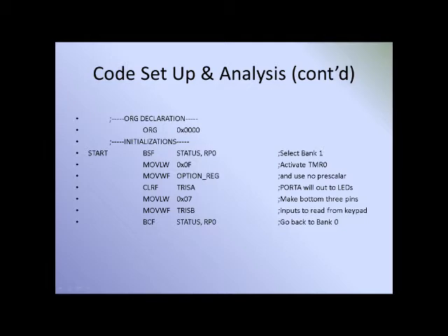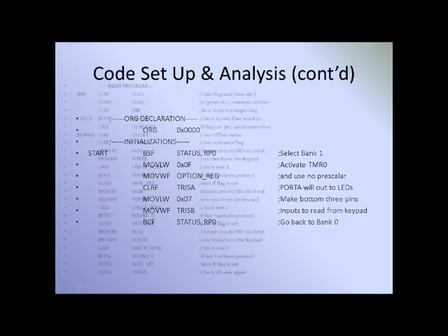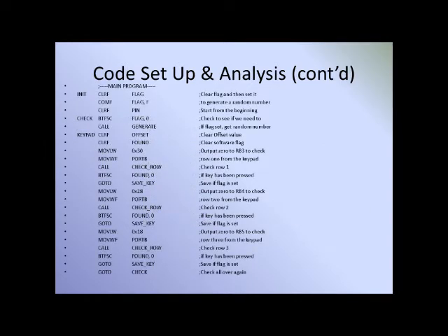No prescaler was used for the timer 0. The main program began by clearing and then setting the first software flag. This software flag was used in determining whether or not a random number should be generated during this iteration of the main loop. A bit test was used to check the software flag, as seen by the BTFSS instruction next to the label named check. If the software flag was set, the generate subroutine was called. This subroutine will be explained later on.